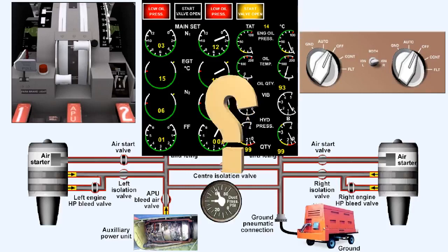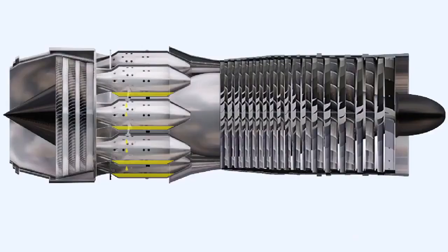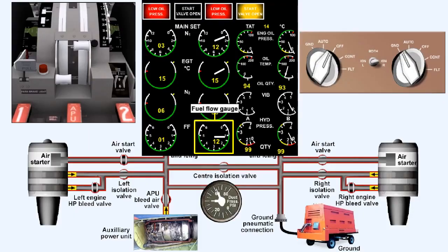However, it may be some time before it's realized that there is a problem, and that the problem is a wet start. Starting malfunctions on gas turbine engines are rare and always come as a surprise, except in the flight simulator, where they tend to become the norm. Thus, there can be a long period during which fuel is being pumped into the engine before the problem becomes apparent. Throughout that period, the combustion chambers and exhaust system are becoming saturated with fuel. The fact that fuel is entering the engine can be confirmed by a glance at the fuel flow meter indication at the instant of moving the start valve to the idle detent.